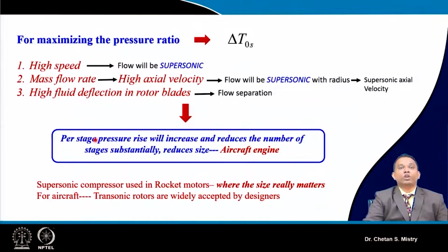In order to reduce the number of stages, in order to reduce the size of the engine, in order to reduce the weight of the engine, in order to improve the fuel economy for future aero engines. Now these supersonic compressors are mainly being used for rocket motors, where size is really a constraint. For aircraft, people started opting for transonic compressors. That's the reason why we will be discussing the design methodology and design approaches for the transonic compressor.